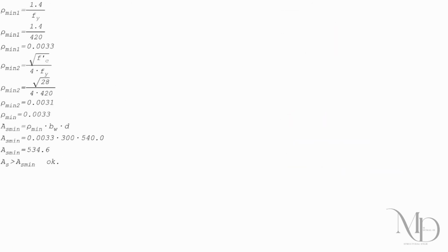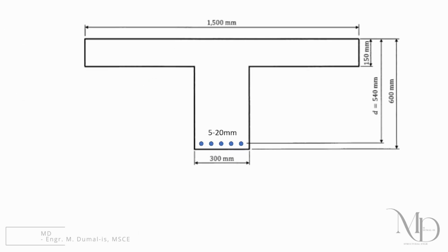Let us now check for the value of the minimum steel reinforcement using the provision of the code. The computed value of the steel reinforcement is greater than the minimum, therefore we can now proceed with the next step. Let us compute the value of numbers of bars using the computed value of As. Once we've completed the calculations and confirmed that everything checks out, the next step is to move on to the detailing. This is where we translate all those numbers into a visual representation by drawing the actual beam details, the dimensions, reinforcement layout, bar sizes, spacing, and everything else needed for construction or documentation.